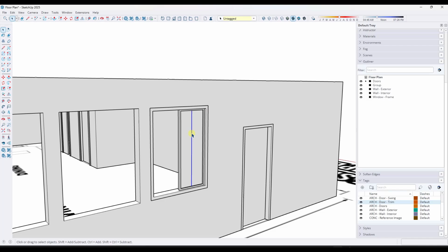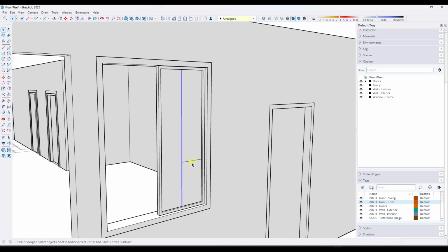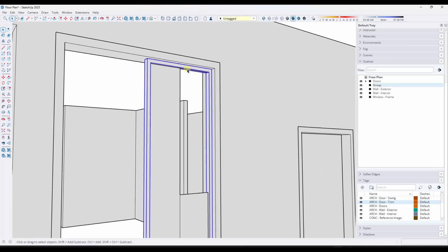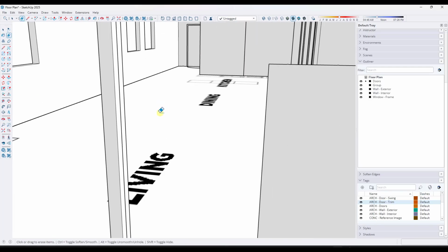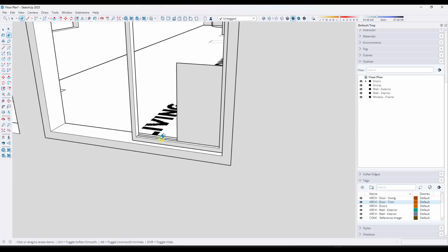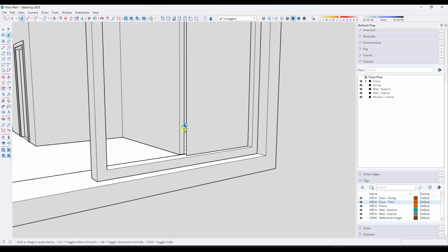So what you can do on an edge in SketchUp is you can right click and do a divide. And then you can move your mouse. Well, notice how that's going to allow me to divide this into 4 segments, or 3 segments is really what we want. But we can use that for each one of our window panes. And so in this case, I'm just going to draw a line across right here. And now I know what the size of one of the panes is going to be. And so in this situation, I'm going to go ahead and delete out all of my extra edges that I drew because I only need to know what one of the panes is going to be. So you can go ahead and delete out this extra geometry. You don't really need it anymore because we're going to model this once. And then once we model it once, we're just going to copy it because, again, we want to reuse as much as possible.